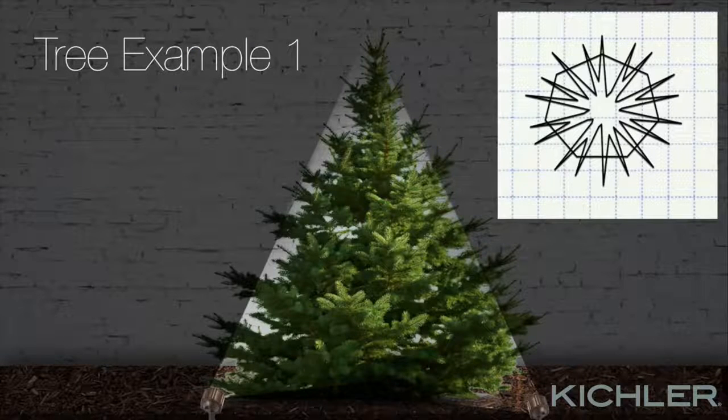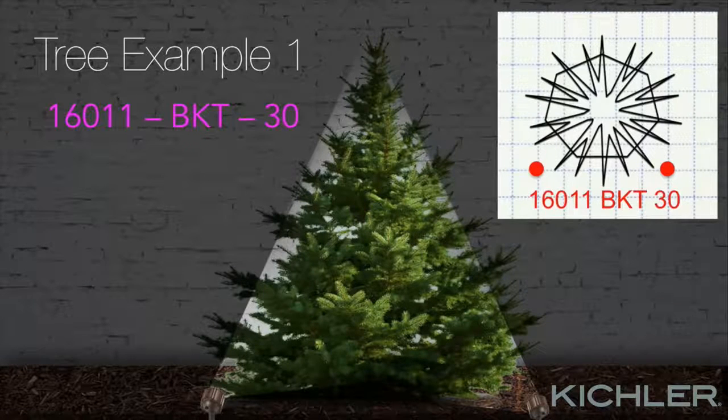When we draw our fixtures on the plan, we will locate them outside of the canopy and identify them with a part number. If we choose the black finish and the 3000 Kelvin temperature, the part number will be 16011 BKT30. If you want to illuminate this tree from both the front and the back, so it is visible from the house, adding a third fixture on the backside would even out the illumination on the back of the tree.